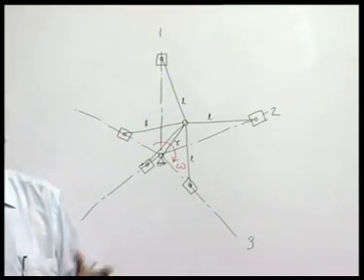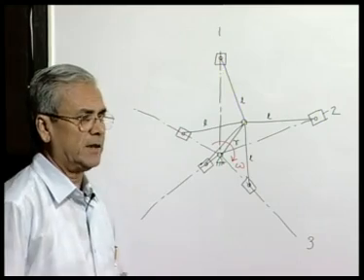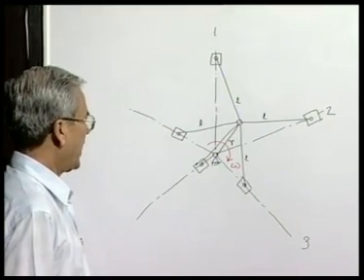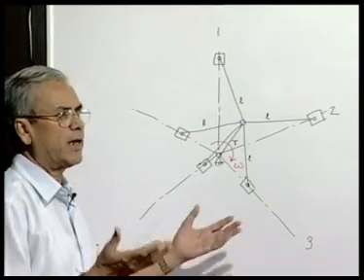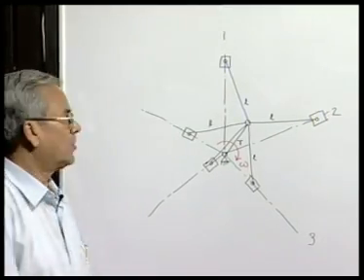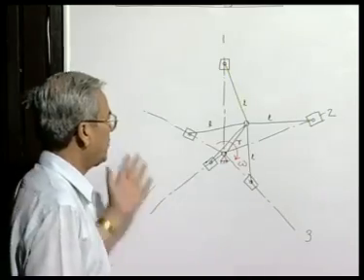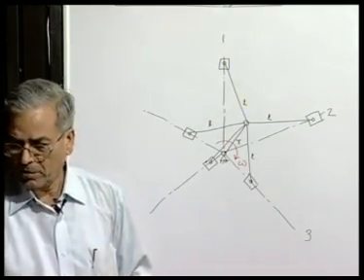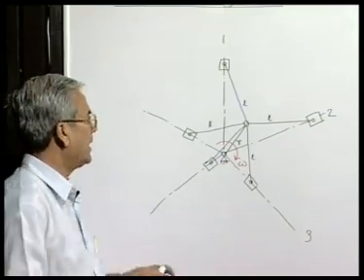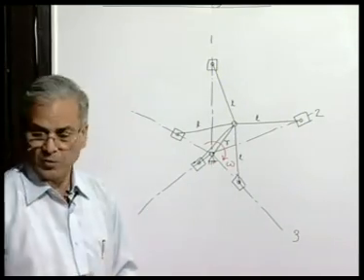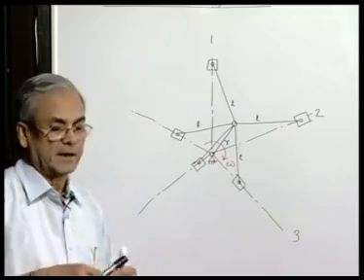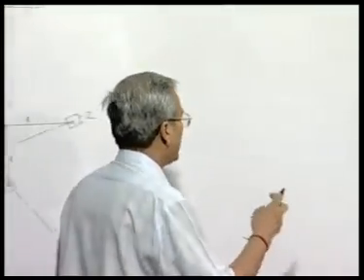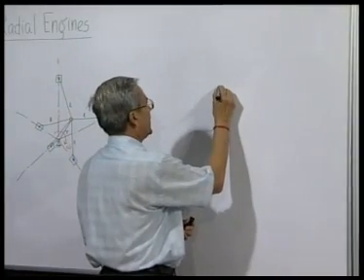Now, the problem can be solved both analytically and graphically. So, we will be satisfied if we can take any one of these two methods. I will use the graphical method to analyze the situation of unbalance or balance in a star engine, or these are also called radial engines. Now, before we can do that, we have to develop another technique which is quite useful, and this technique is called the method of direct and reverse crank.